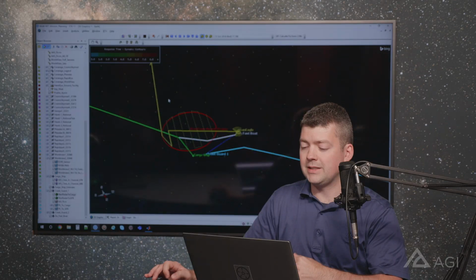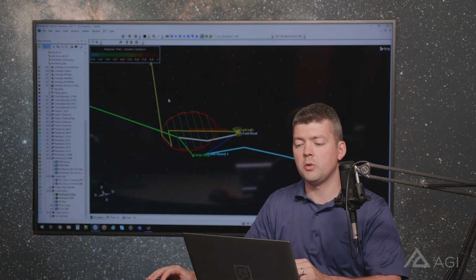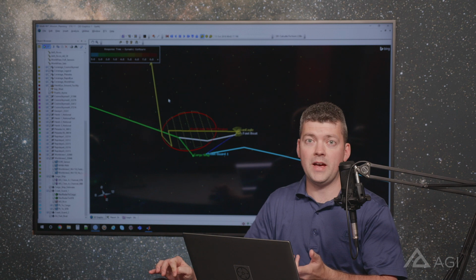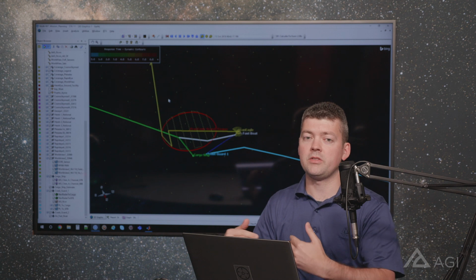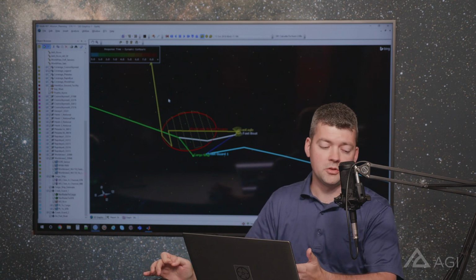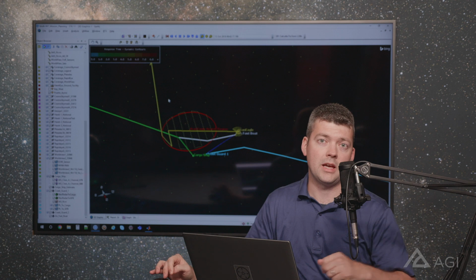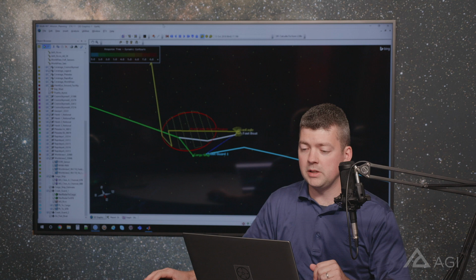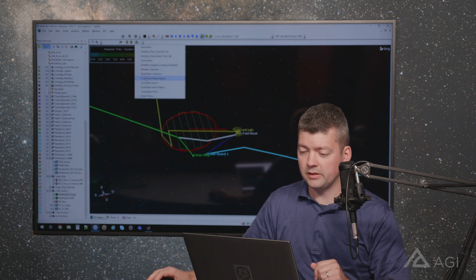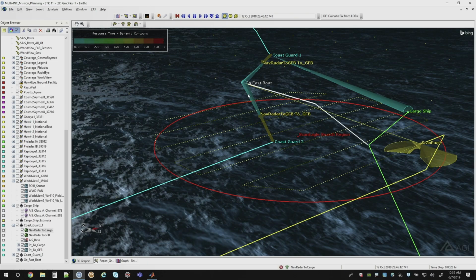So then there's also a time as these two cargo ships are approaching where both of their radars can now detect the fast boat. So maybe they both get a signal, you know, hey, I've got a hit at this azimuth, possibly this range, got another hit at this azimuth, this range. And so we could even do simple direction finding in STK to do some basic triangulation and figure out where that point would be. So we've got, here we go, triangulate point. In this case, we actually used STK's vector geometry tool, part of the analysis workbench, to do that triangulation calculation at that time and come up with a potential target point for the fast boat.